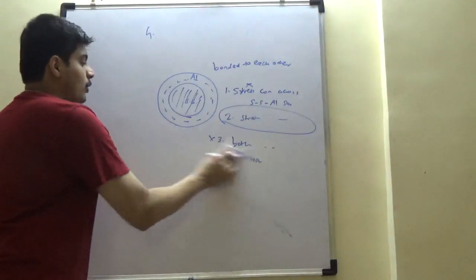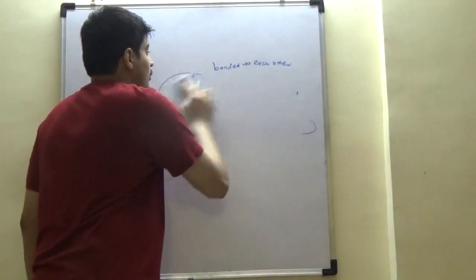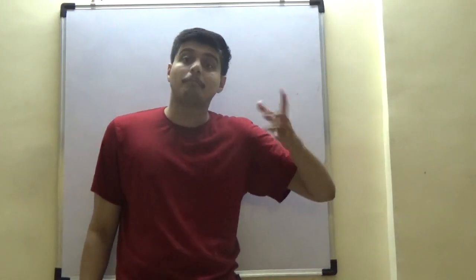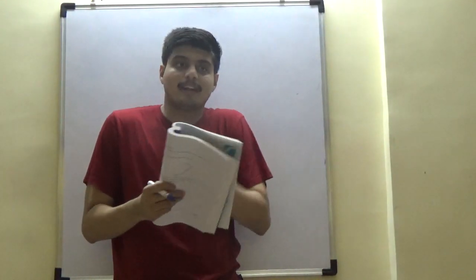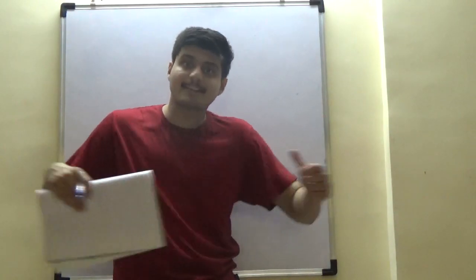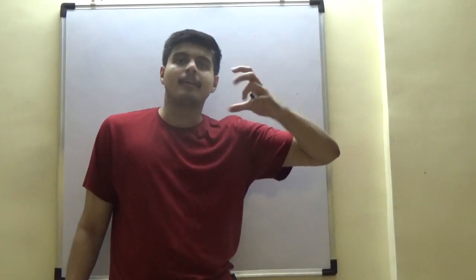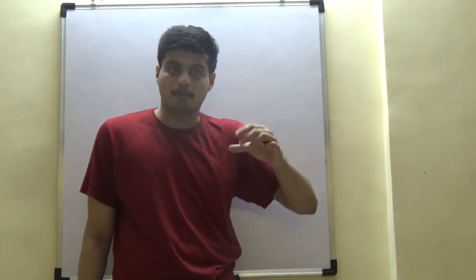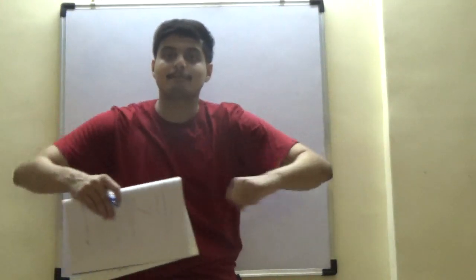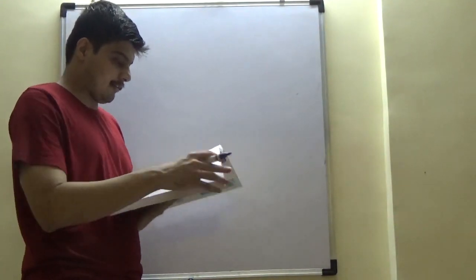Because otherwise there would be a slippage and material coming out, which, because of bonding, is not allowed. So in bonded composites, stress cannot be continuous because of different material property, and in fact to hold them together, the glue is getting that additional stress. So the glue, or the weld, is getting stressed with that difference of shear stress between SS and aluminium. If SS has lower stress because of higher G and aluminium has more, that delta is balanced by the bond that keeps them together. Another insight. So this is the GATE problem that we looked at.